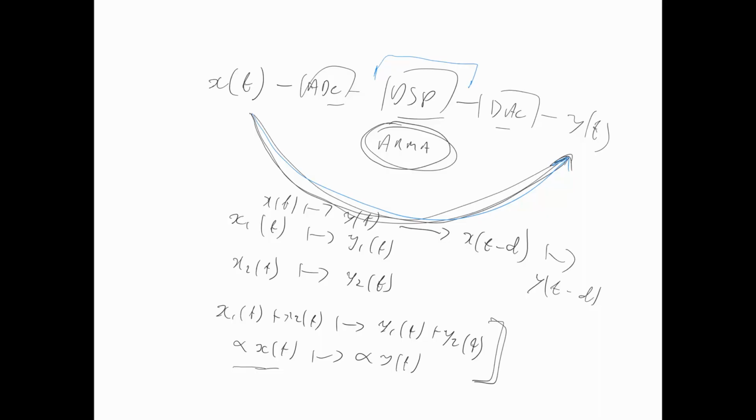But with a linear time invariant system, if we know what the system does in response to a signal x1, and if we know what the system does in response to an input x2, then we already know what it does in response to the input x1 plus x2. And in fact, what it does to the input 5x1 minus 10x2. We have gone from knowing how the system behaves on a small number of inputs to knowing how the system works on a very large number of inputs. And if we're very lucky, maybe any input can be represented as a suitable linear combination of our input signals.